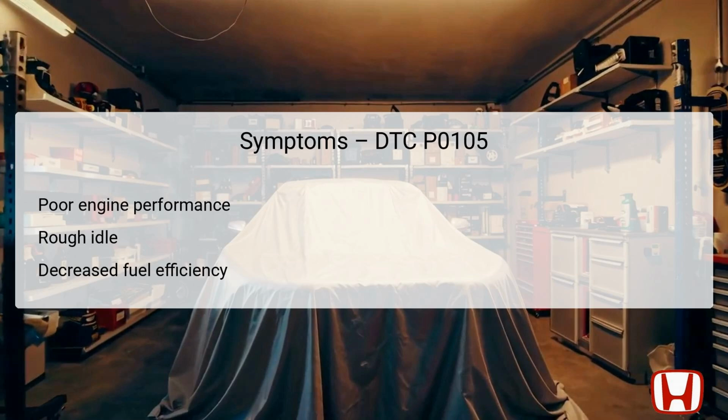When DTC P0105 is triggered, drivers may experience several symptoms indicating a problem within the vehicle's engine management system. Poor engine performance is one of the most prominent symptoms, as incorrect air-fuel mixtures can lead to a lack of power during acceleration. Rough idling could also occur due to fluctuations in engine performance, making the vehicle feel unstable while